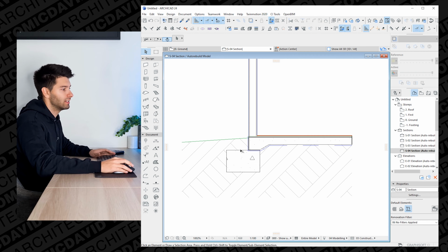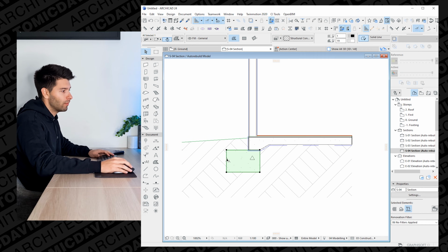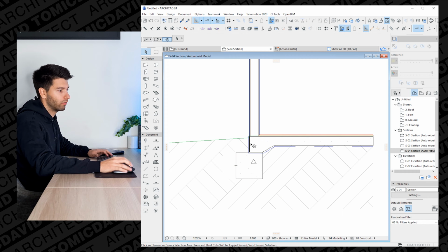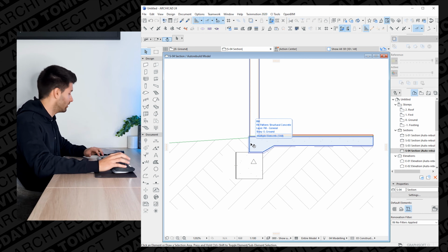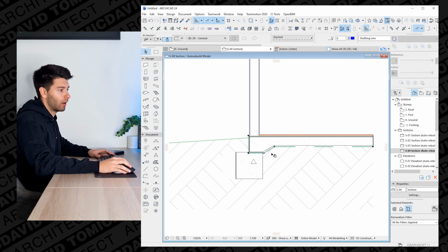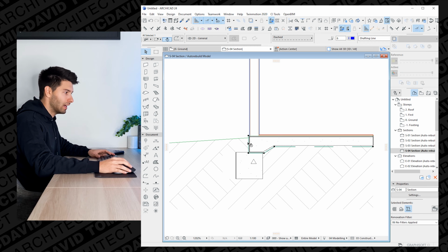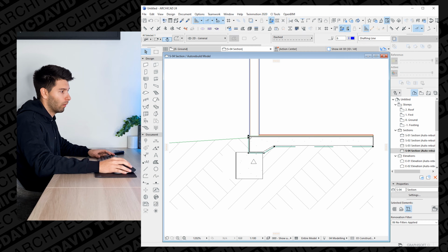What you'll see straight away here that's different is that footing probably won't be that big. We can drag that now back maybe about 150 mil to make it a smaller footing. Again, the engineer will detail this, and this waterproofing membrane is actually going to be very different to what we had in the brick coursing. Instead of going under this footing, we're actually going to go all the way around.